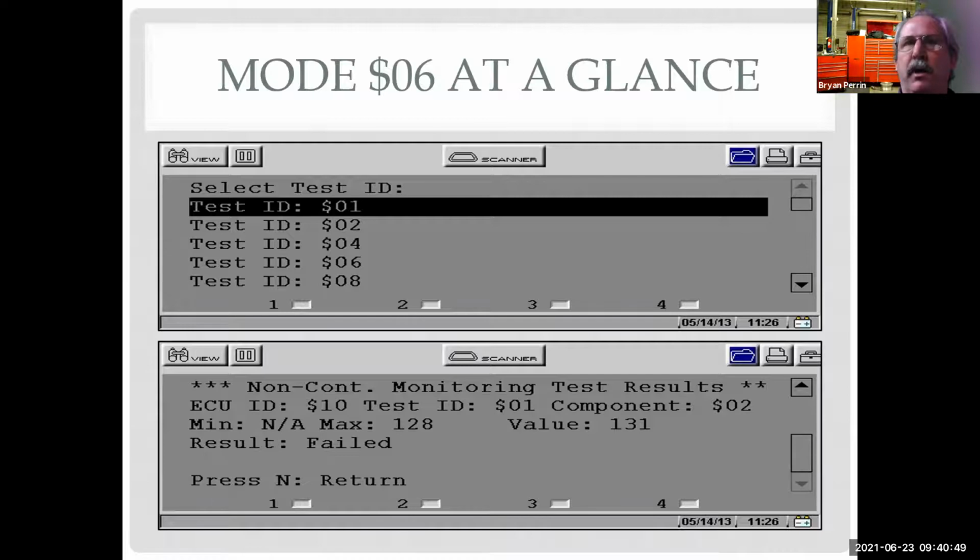Now, keep in mind, prior to 2008, O2 sensors were only tested once per warm-up cycle. So that O2 sensor would get tested within the first 20 minutes of operation, normally in the first 10, and then we're just going to believe everything it tells us for the next 4 hours of driving, where the catalytic converter monitor is tested at different times or further on during the drive.